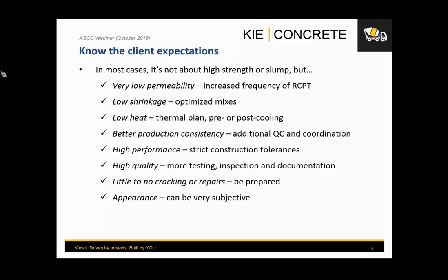And then appearance is something so subjective, but it always shows up in different architectural concrete projects. You need to understand what that means. Do I need to make a mock-up? Do I need to work on a certain material consistency, so I don't change my different sources of materials and affect the color of the concrete? And many of you that are in building construction are very aware of these requirements when you get into architectural concrete.